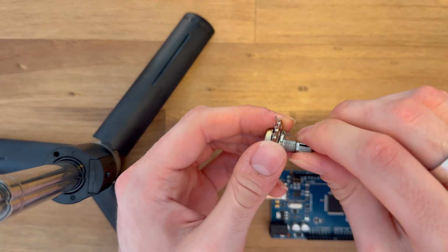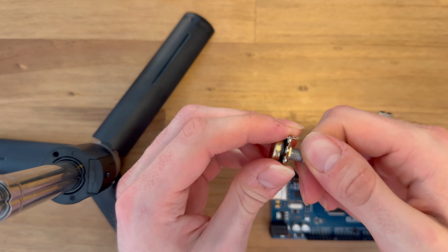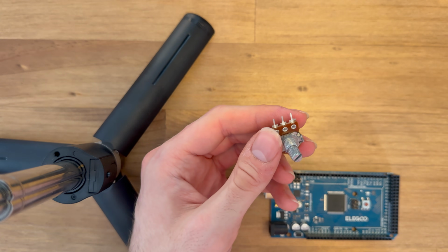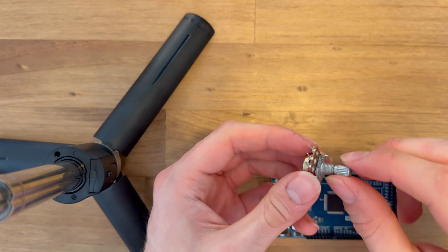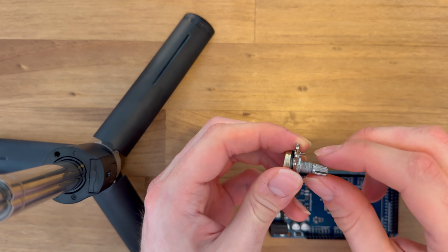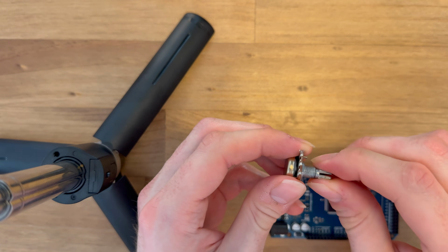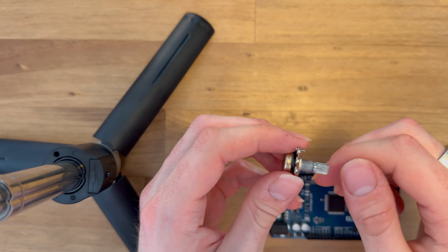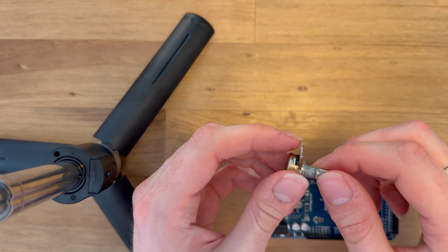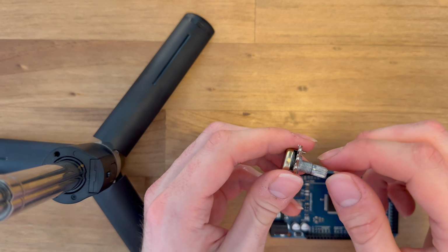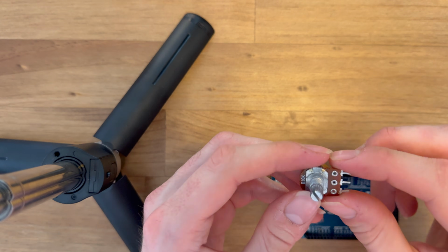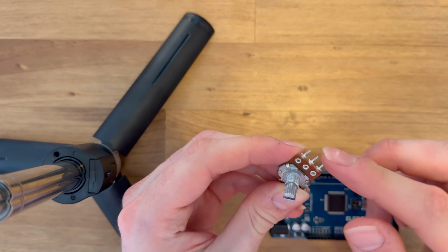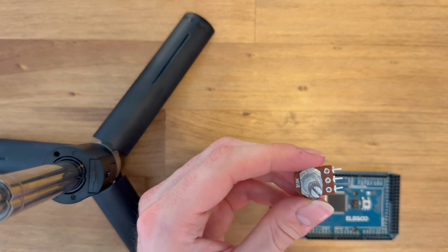I have numerous potentiometers in my setup. On the overhead panel section, I have 3 of these to control the temperature in the flight deck, aft and forward cabins, and they also are responsible for controlling the lights in my setup, so the navigation display, PFD, ECAMs, brightness, that sort of thing as well. So to wire them, we have 3 pins coming off, and I'm going to use my jumper cables again.